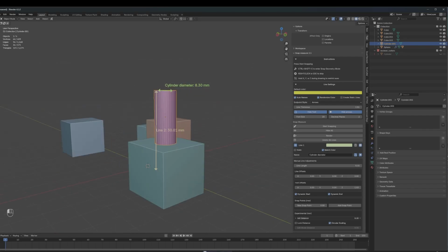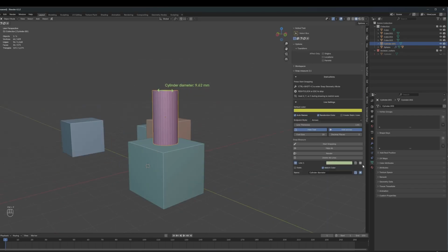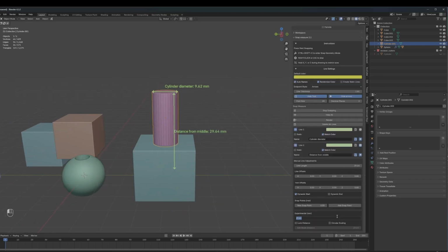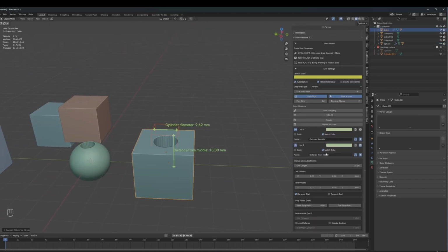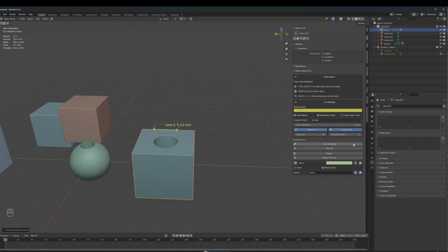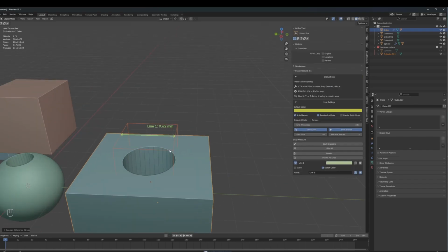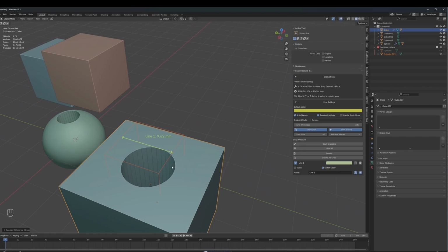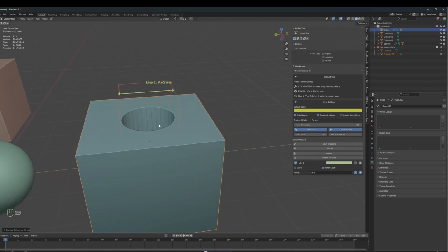We can use the measurements to move objects, or part of objects with respect to another. This creates a powerful workflow when creating parts for 3D printing. If we use this behavior on booleans, we can work non-destructively and easily modify our objects. The best way to work non-destructively is to measure on the booleans themselves. If a mesh has measurements and is modified, this will change the indices of the mesh, thus corrupting the measurements.